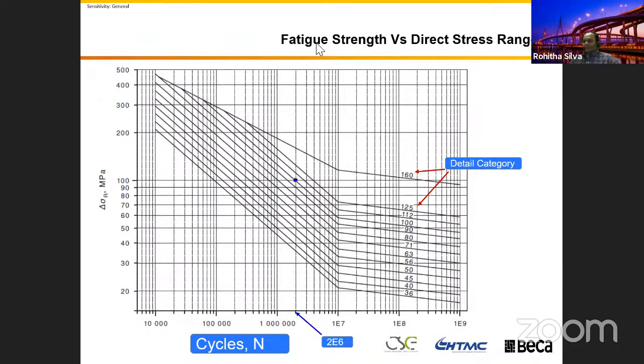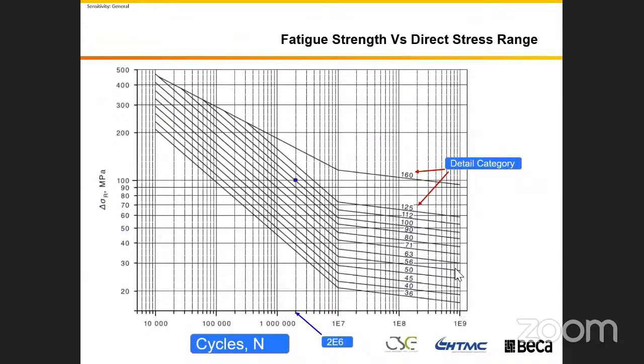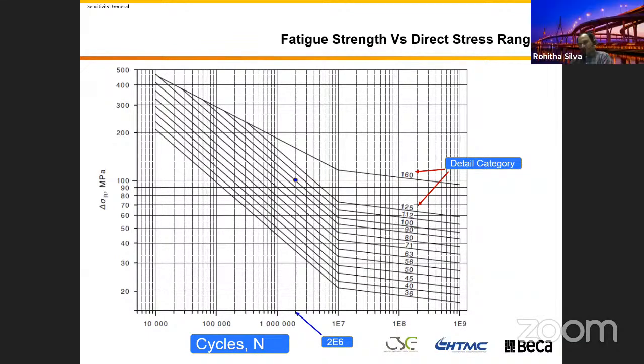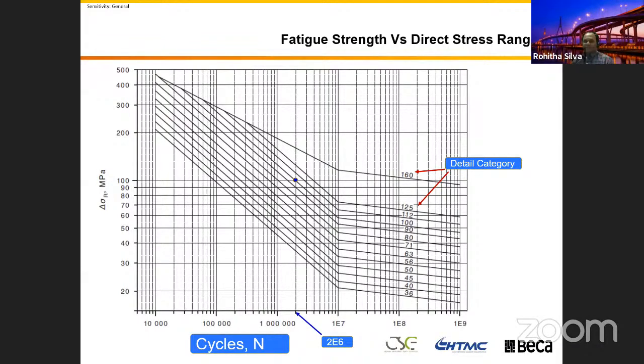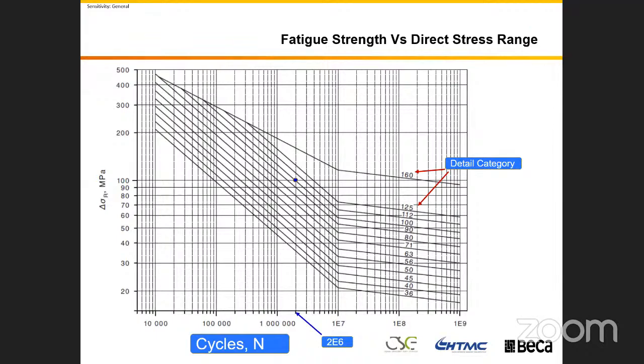Yeah. So Rohit, I can add to that. We design pavements like that. Fatigue. If you get those road design guides, you will have the same equation for pavements. To make sure that the concrete strength is below fatigue, we use Miner's hypothesis for the fatigue loading, to get the cumulative damage in the pavement, right? Cumulative damage in the pavement. Yeah, good to know that bridges are designed the same way. That's good. Thank you. Thanks, Pratap.